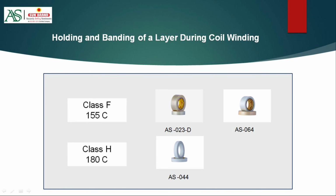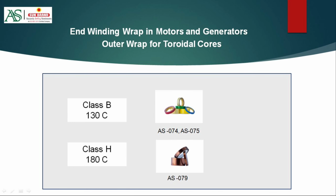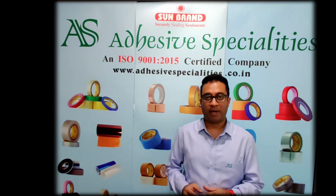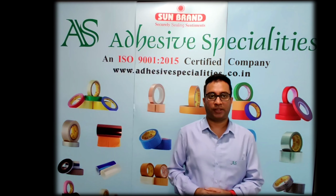Common application examples. For holding and banding of a layer during coil winding, you require a tape that has high tensile strength and typically class F and class H thermal insulation. For end winding wrap in motors and generators, for wrapping the phase insulation, also for outer wrap of toroidal cores, good conformability is required, and those are low tensile strength tapes. For oil transformers, we need to use tapes which are oil compatible and high tensile strength with good absorption and have class B thermal class.